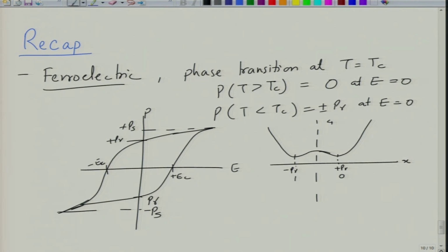So it is basically used for binary data storage, that is why it is called 0 or 1 state. But nevertheless it is basically the position, either plus X or minus X, at which the titanium central atom sits. So basically a cation is shifted with respect to the anion polyhedra center by a small amount, giving rise to a net dipole moment.